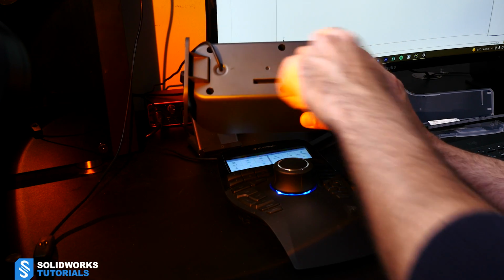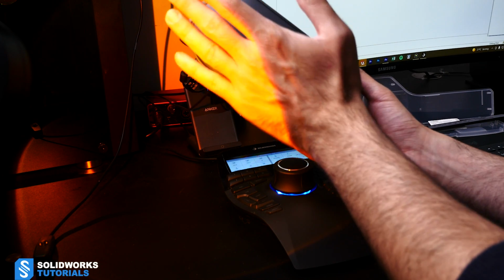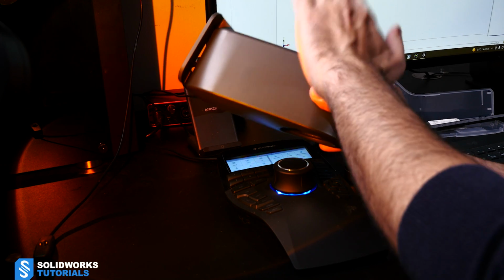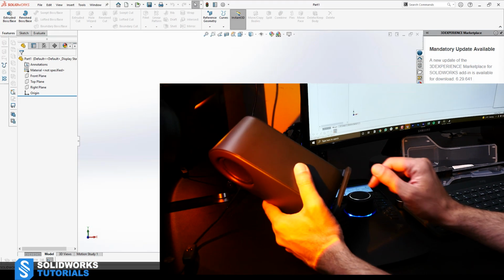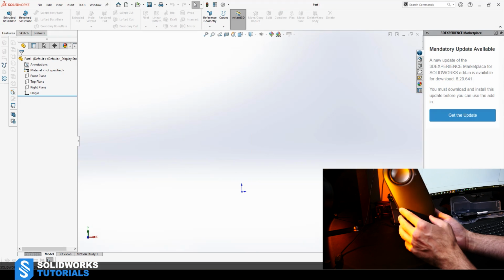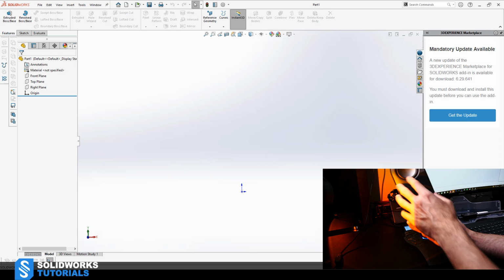It goes back to some sort of a rectangle with rounded edges. So on the back, we have a different geometry, and on the front we have a different geometry. And since these two are on two different planes, the perfect tool, a lot of you might know that already for this, is Loft. I could show you that too in a different video.